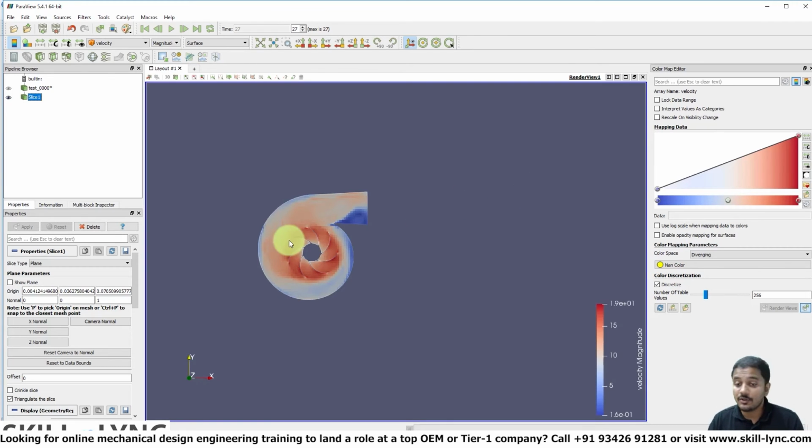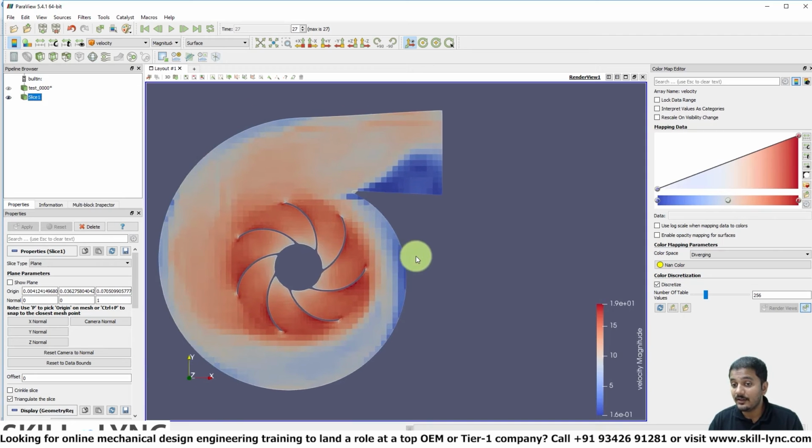In this particular case, it's not, because there is flow reversal, which means in order for the mass flow rate to be achieved, you can actually have excess mass leave from the top area so that the net mass flow rate is equal to your boundary condition. In other words, the equations are working in your favor to reach the boundary conditions, and that shouldn't be the case. Ideally, when the flow is being calculated at the boundaries, the solution naturally reaches the boundary condition value.